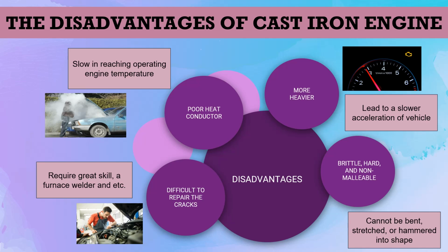The third disadvantage is the cast iron engine is difficult to repair when cracked. Okay, actually the iron engine block crack can be repaired, but it is still pretty difficult as it requires great skill, a good furnace welder, and so on to repair it.